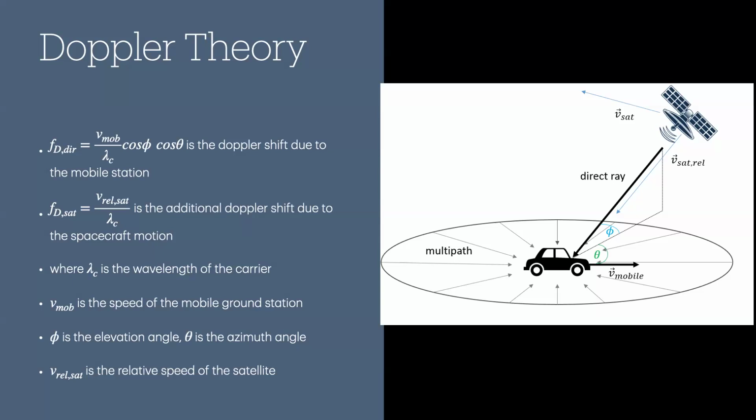So it's a simple enough equation. The frequency at the ground station is given by the velocity of the mobile ground station divided by the wavelength, times sine theta, sine phi, cos theta. That's just the angles to the spacecraft. You don't need to go into the details about that. And the frequency from the satellite's point of view is the same, but just with the relative change in frequencies. It doesn't have to track you, you have to track it. You do the work on the ground. You don't let the spacecraft do the work because that uses resources which you don't want to use. If you can put a resource on the ground, you do that because it's more efficient. You've got more payload that way.